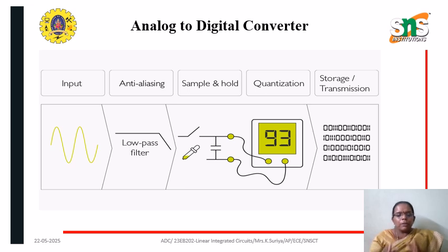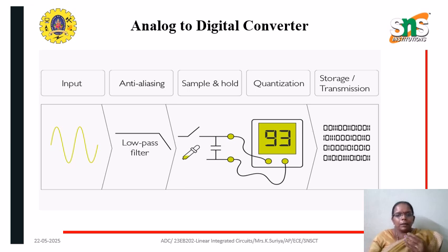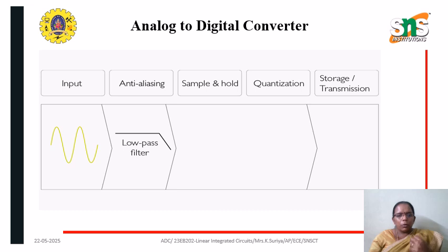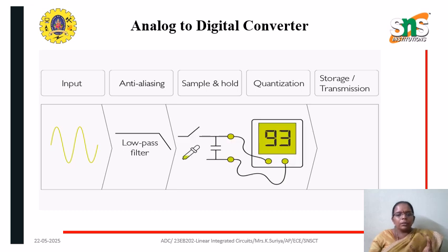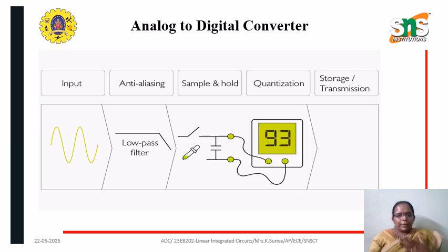So the working principle of analog to digital converter is very, very simple. So first the input analog signal is fed to the sampler circuit. The sampler circuit takes the samples from the analog signal with respect to the discrete time with the help of the sample frequency. Now the samples are held for some time in the holding circuit. After the holding circuit, the quantizer output is fed to the encoder circuit that actually generates the digital signal in the binary form.